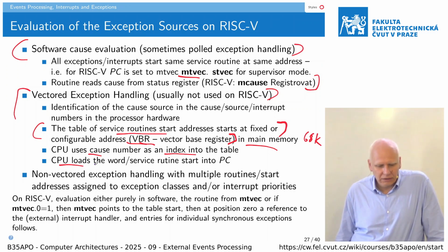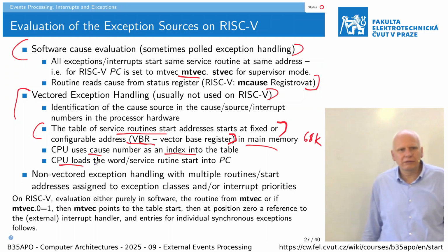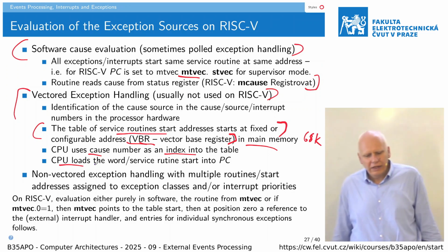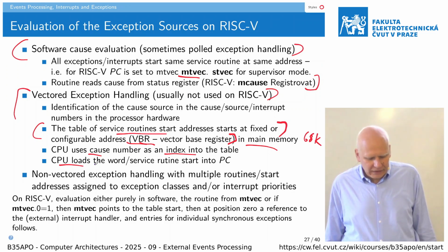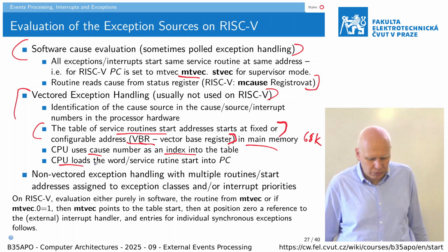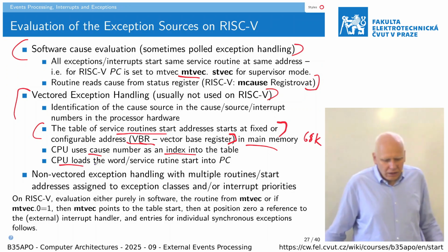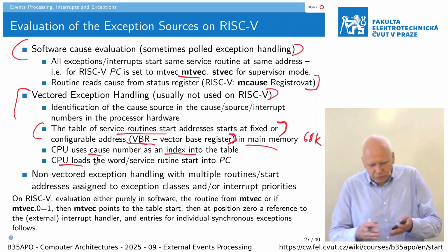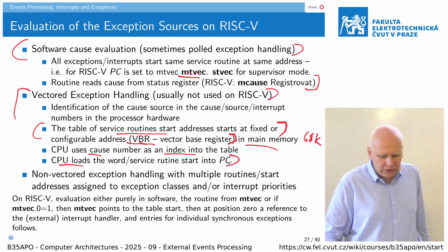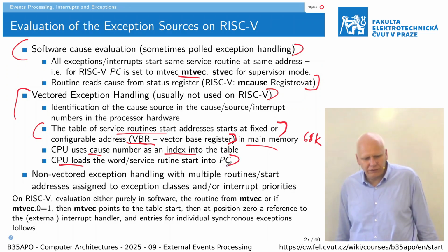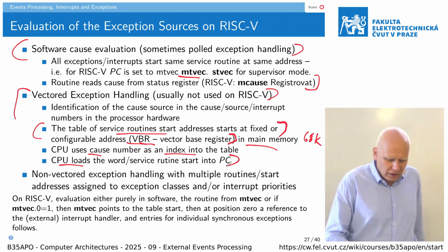But it has a disadvantage that you usually want to have some common part of all external interrupt processing, and you need to route all those routines to a single point. So it allows fast reaction, but usually for a bigger system it is not a big help.